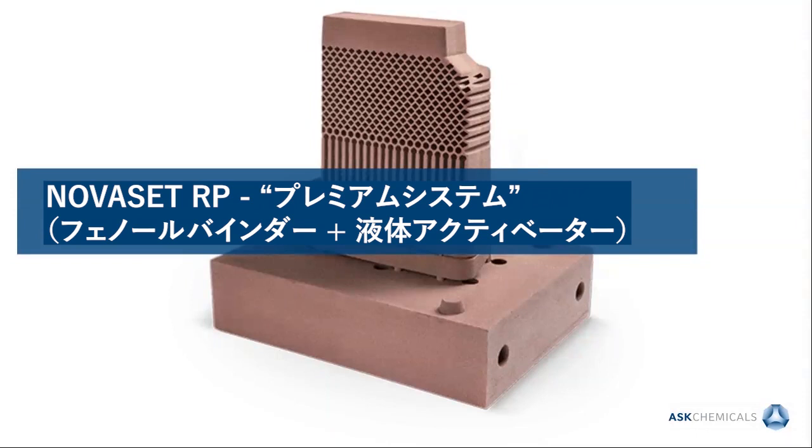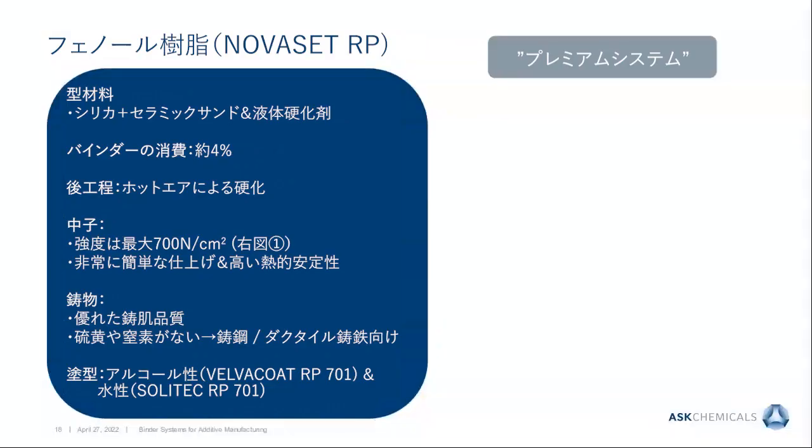Let's look at the phenolic binder system NovaSet RP, which is also combined with a liquid activator in the sand. And here the predominant sand systems are silica sand or synthetic or ceramic sand, and the liquid hardener is integrated into the sand. Binder consumption is a little bit higher, around 4%.